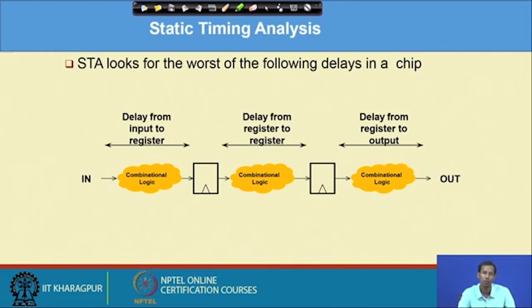But in a combinational circuit, if you change any signal, that will automatically reflect at the output. But in a sequential element, if you find the edge, then it goes for checking the value present at the data, and based on that data, the output will change. So that is why the clock gets the highest priority. That is why a sequential element is clock dependent, not data dependent. Okay, got it. And because of that property, if we put the registers in between, C1, C2, C3 become independent of each other.